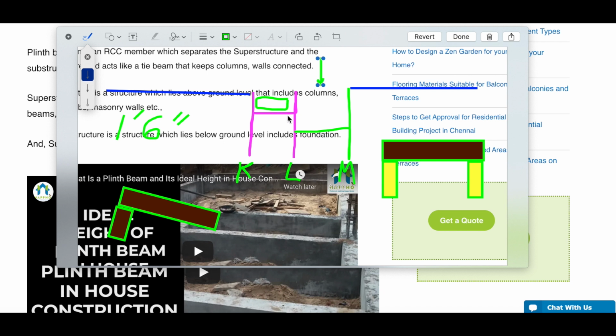This probably bought the 7 minutes before this finally buckled, continuous buckled, failed, rotated down, and then caused the rest of the collapse to progress with the extended, unsupported spans of the first floor, resolving itself right about here, dropping down.